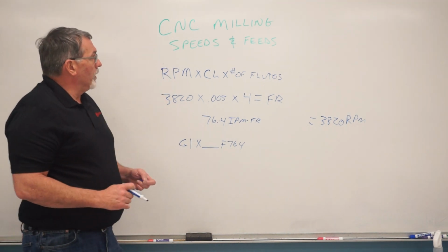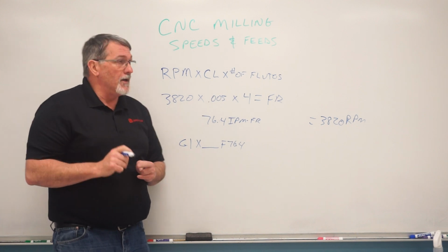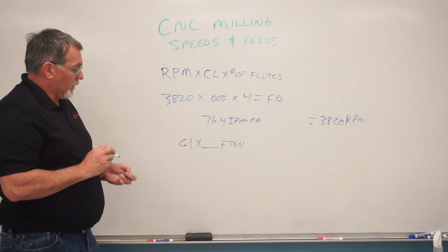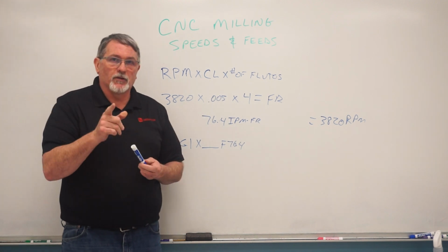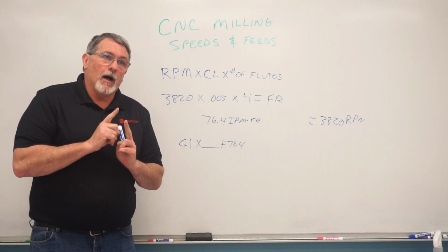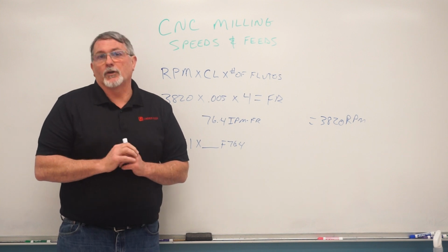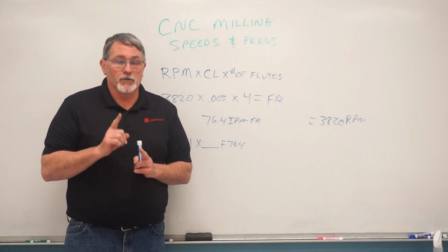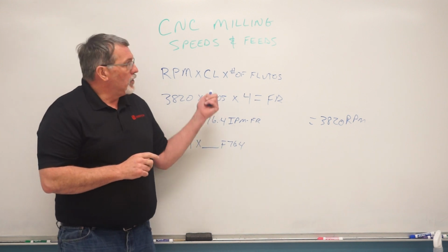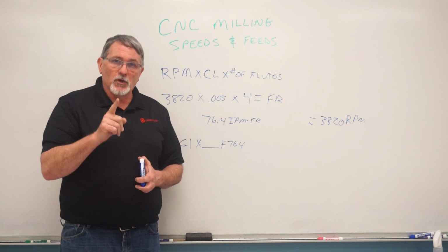So those are our 2 formulas. These are really important formulas you guys want to learn and memorize, our speed and our feed formulas. Write those down, keep them at your fingertips. It'll help you a lot when you're programming, or when you're on the machine and you have a feed or speed issue, you'll know how to recalculate those and check to make sure those numbers are right. You do want to check that every time you write a program. Use these formulas, calculate your speeds and feeds correctly each time. Thank you, keep making chips.